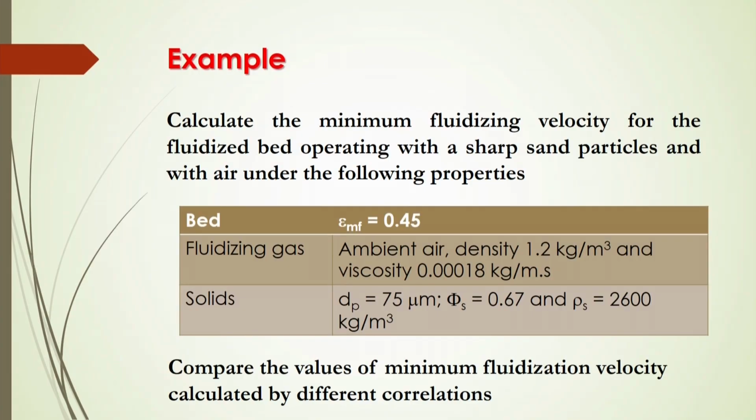So, water has higher viscosity than gas, that is why this minimum fluidization velocity will be reduced. And another example, I calculate the minimum fluidizing velocity for the fluidized bed operating with sharp sand particles and with air under the following properties.